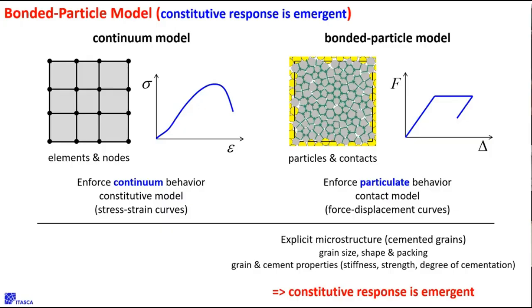You go through your core with all these cylinders, and there's a bunch of them that cut through joints and break apart. You just take the good ones and you test those. So those are intact rock. But at the scale of 8 by 4 meters, that rock is going to have some sort of joints. It's going to have other structures at a bigger level, which is going to make it weaker than if that wasn't there. And we call this rock mass scale versus laboratory scale.